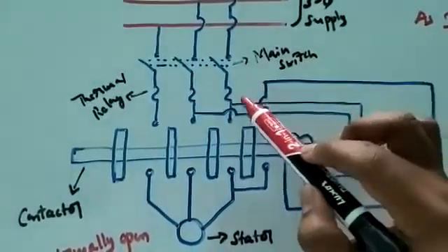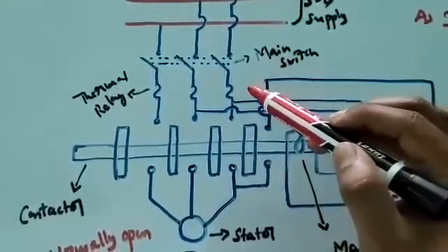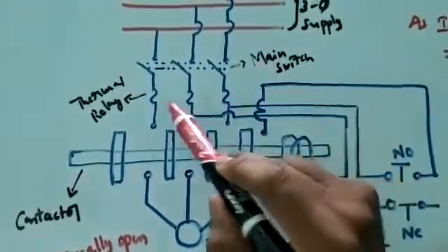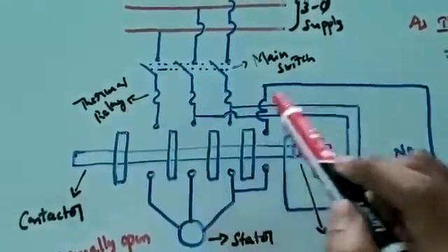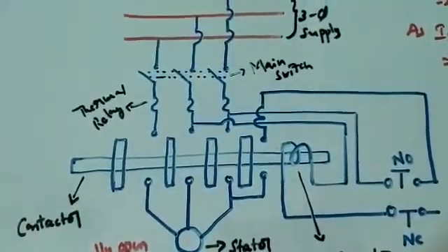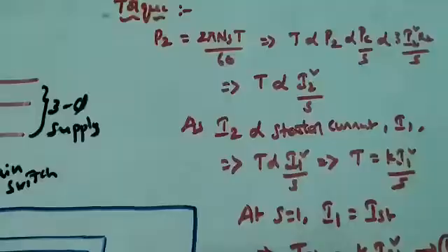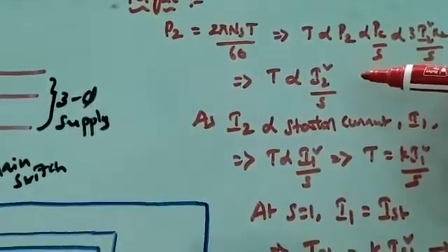And moreover, if you are having any kind of overloaded conditions, then excessive heat will be produced in the motor. In order to avoid that excessive heat, thermal relays will be used, right? So this is the working procedure of DOL starter, right?